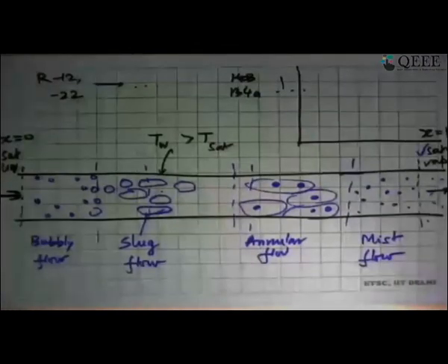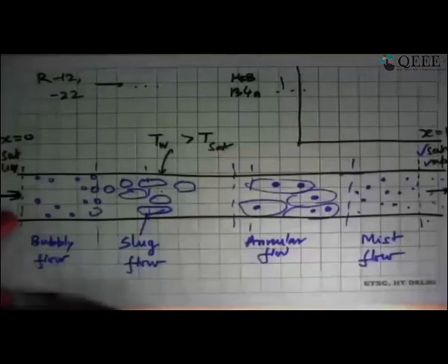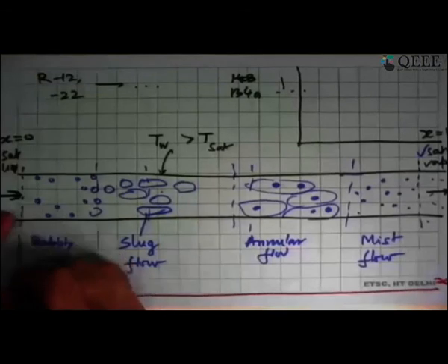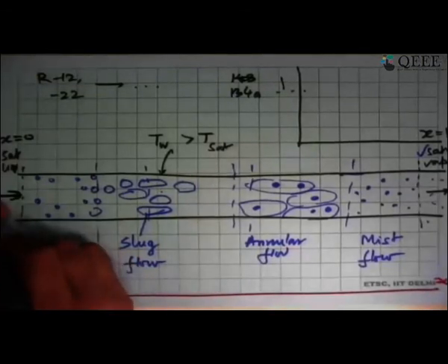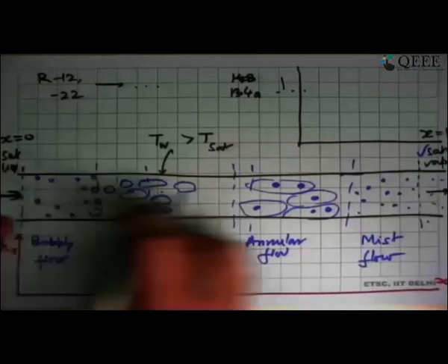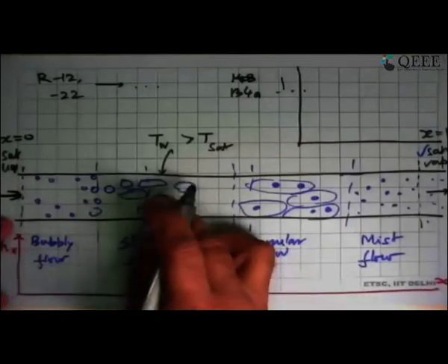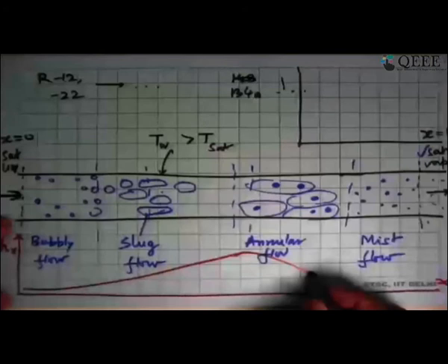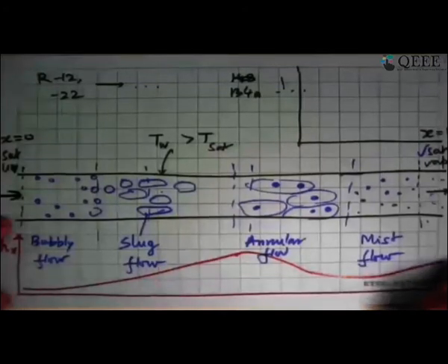And if you have to plot the convection heat transfer coefficient along this direction, so this is x, and on this side we plot hx, which is the local heat transfer coefficient. Then we expect that from here to here, somewhere here it will increase, and then because mostly vapor is now coming in, it will start to decrease, and then again slowly increase.